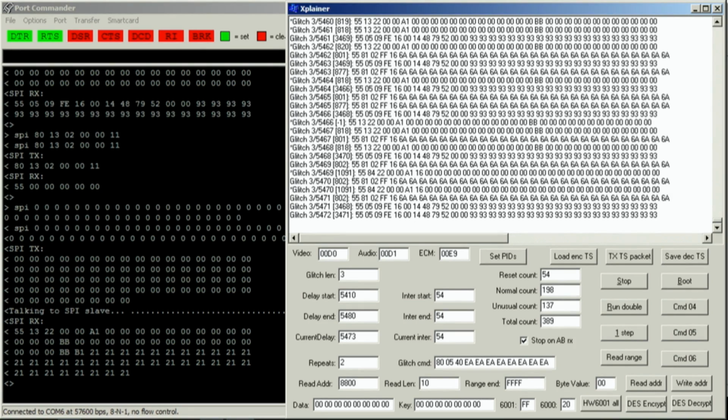So I wrote a simple application that performs the glitch searches and then can interact with my code payload backdoor I've installed in RAM. This program allows me to enter an address and length and have data returned, or to write to memory, etc. There's also support for setting the key and data and performing DES encrypt or decrypt using the hardware peripheral inside. At this point, I notice a few points about this chip.